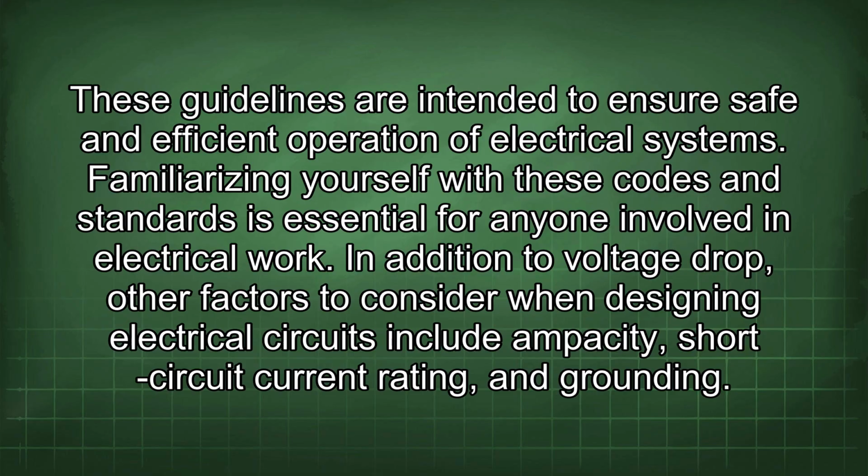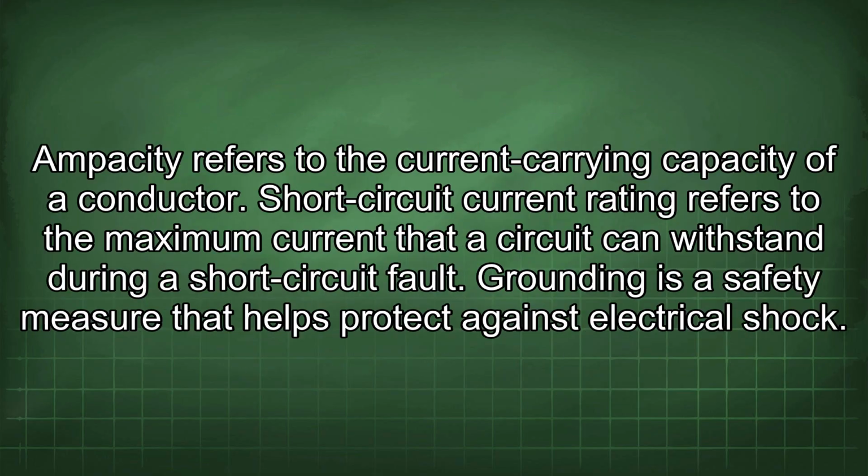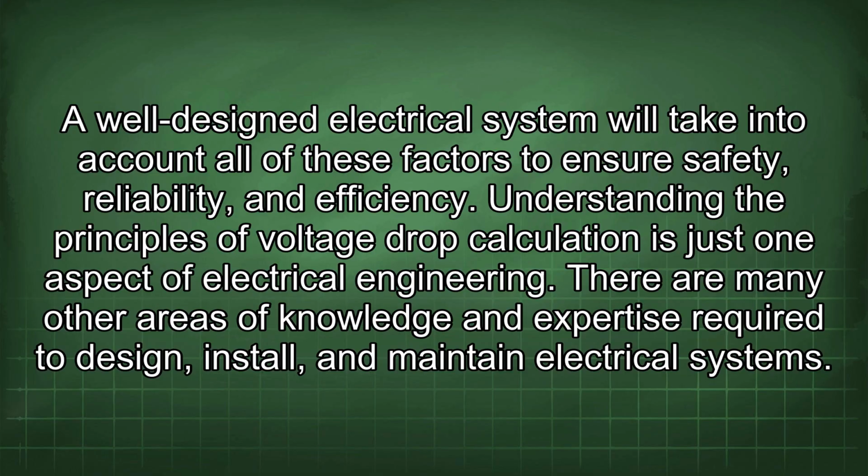In addition to voltage drop, other factors to consider when designing electrical circuits include ampacity, short circuit current rating, and grounding. Ampacity refers to the current carrying capacity of a conductor. Short circuit current rating refers to the maximum current that a circuit can withstand during a short circuit fault. Grounding is a safety measure that helps protect against electrical shock. A well-designed electrical system will take into account all of these factors to ensure safety, reliability, and efficiency. Understanding the principles of voltage drop calculation is just one aspect of electrical engineering.